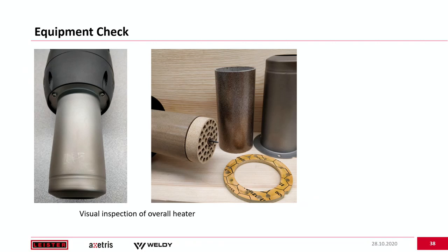But more importantly, maybe you want to take the heater tube off of the heater to make sure that there's no signs of stress, like cracks in the element itself, or you've got a good mica tube and the seal is just right. This is a good way to make sure that you can keep your equipment up and running. You don't have any failures during your manufacturing process.